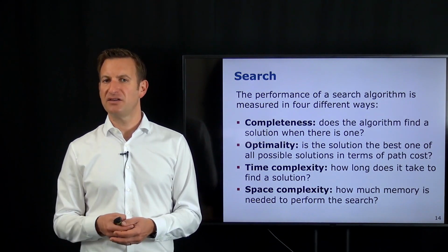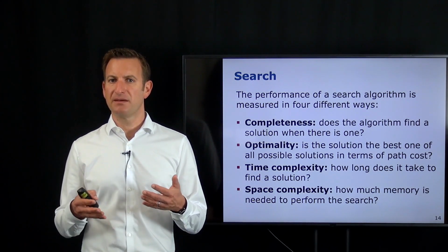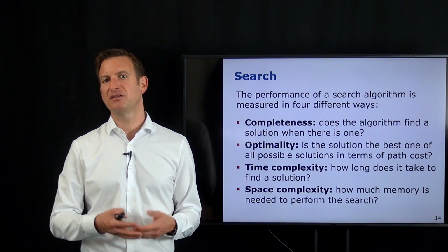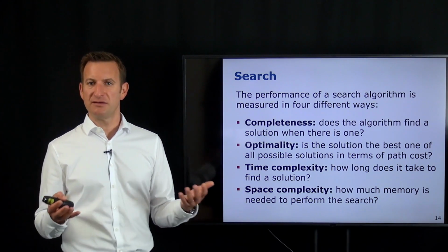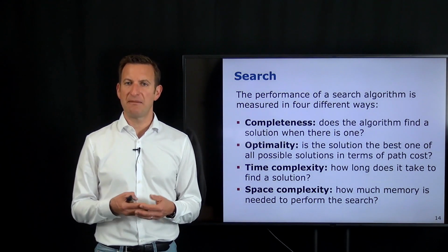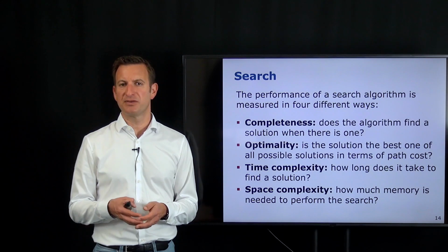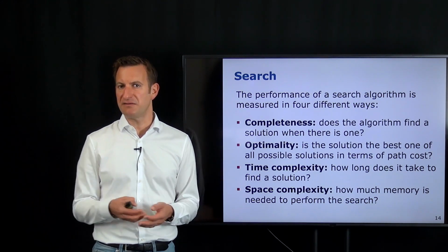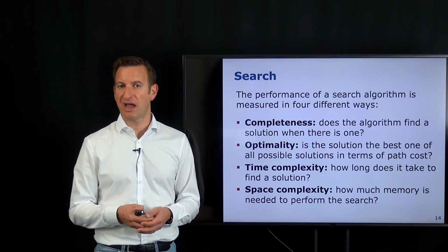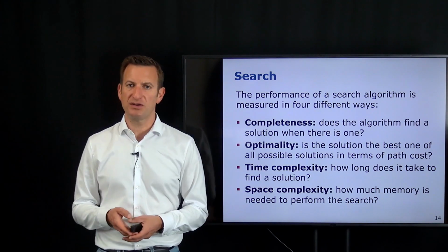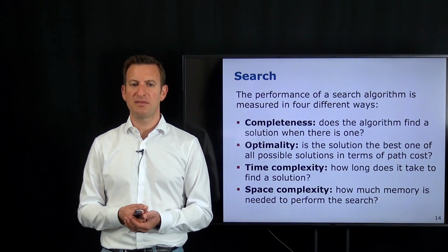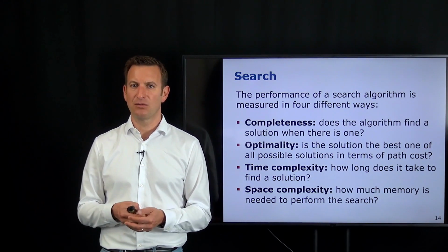It may be the case that, even though there exists a path, it's unlikely or cannot be guaranteed that the system actually finds this path. This can happen for sampling-based planning algorithms, especially if you don't have an infinite amount of time, only a finite time horizon. Optimality is a second very important criterion: is the path that the system actually generates the optimal path or not?